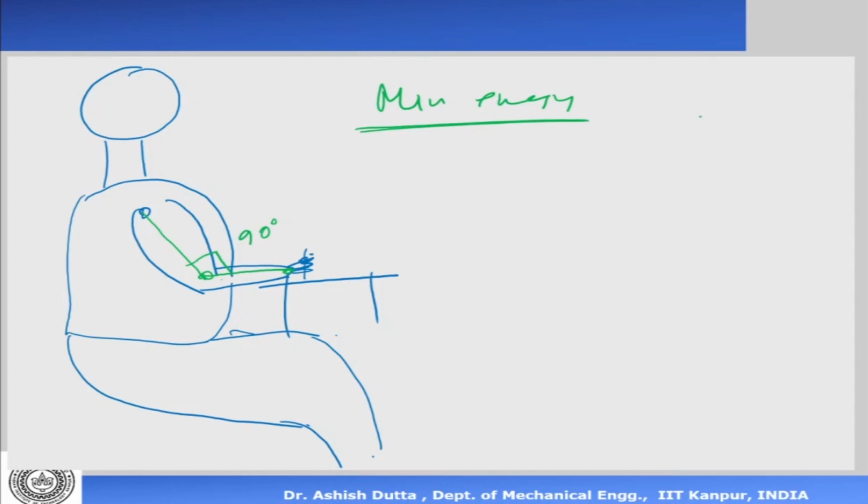It is not only that we are studying robotics and talking of mechanisms, but this is valid even for us, because in our legs, hands, arms, body, we are also linkages, right? So whatever we are studying is valid for us also. Minimum energy, we have seen, you can ensure by maximizing the determinant of J. That's very interesting and very important for us, because we are always interested in finding paths where your energy gets minimized.